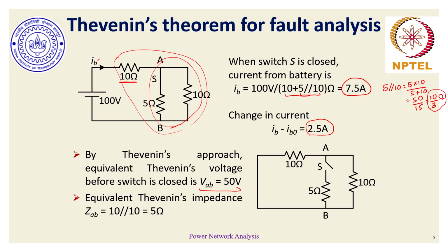Current sources, why are they open circuited? When the current sources are open circuited, the corresponding current cannot flow, and hence the power or energy cannot be delivered by the corresponding current source, and that is the reason why we are trying to make them passive. One could also argue why voltage sources are only shorted, why are they not opened? If you try to open up a voltage source, potential will still exist, and that's the reason why the circuit won't remain passive. Same thing for current sources: why are they not shorted? Because still current can flow and it could pass on through some other circuit element.